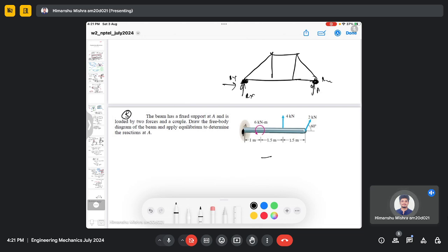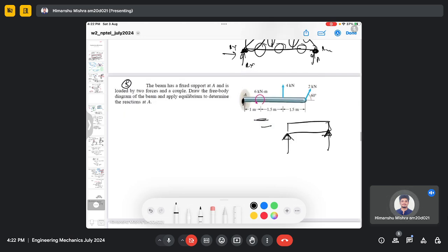Once we get the reaction forces, then we can solve for the forces in each member of this truss by the equilibrium method or by another method. Similarly, in this cantilever beam, or there are various kinds of beams, a simply supported beam, for example, which is just supported at the two ends, the first step is to find the reaction, and then we do the further analysis.